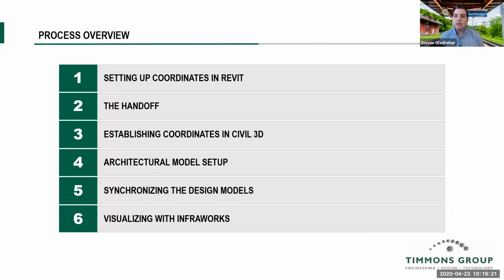So you'll recall that in step 4 of the process, the workaround that we applied to hedge against the 20-mile limit of Revit was we created a civil model that we linked in origin to origin, or however you link in your other discipline models. And we defined the survey point in that model. That allowed me to have the flexibility of linking in a civil Revit model without exceeding the 20-mile limit in my other models.